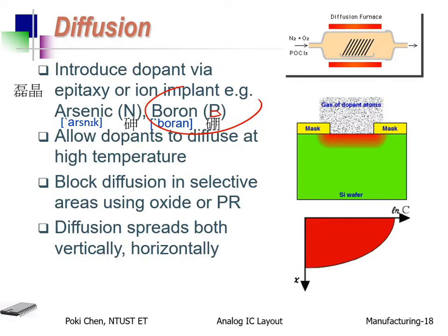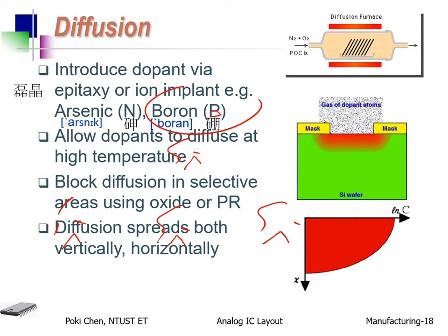Anyway, as I mentioned, we have silicon here, silicon there, right? If the boron atom gets high enough speed to kick out this silicon and take its position, congratulations, we doped somebody there. But to keep the same crystalline, be careful.